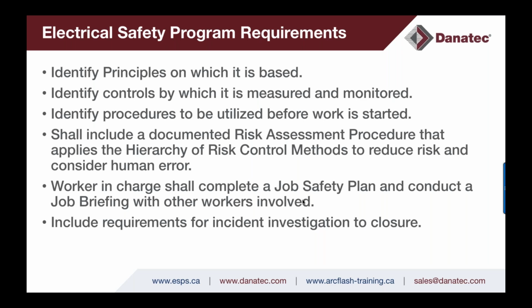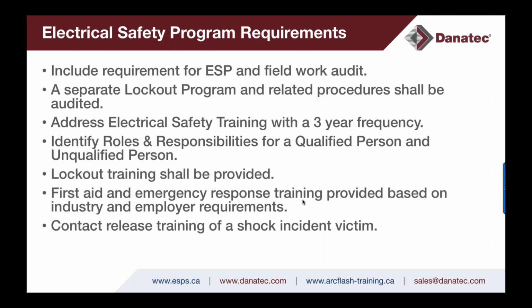So what I've implemented in the Danatec electrical safety program is an incident investigation form for electrical incidents specifically. And that can be used with the overall incident investigation form or a software tool, and it ensures that specific electrical information is collected from the incident scene. This is critical to doing a root cause analysis of the incident, is that information is collected at the point that the incident occurs.